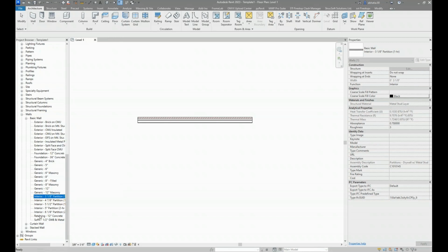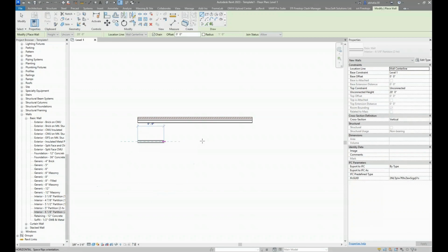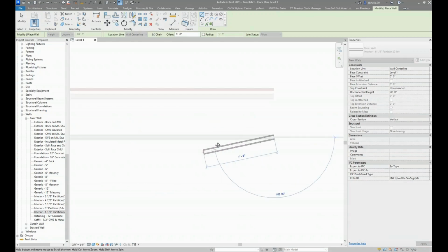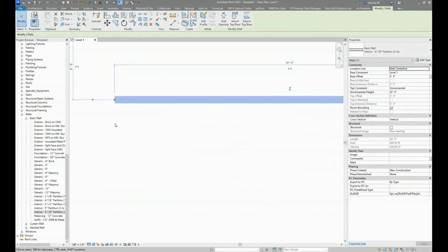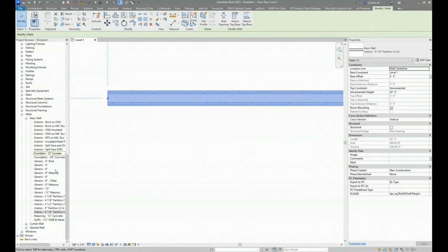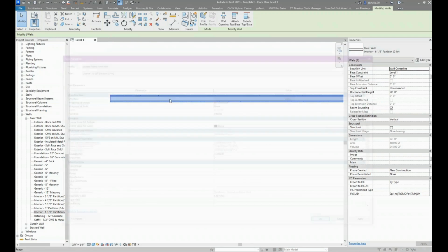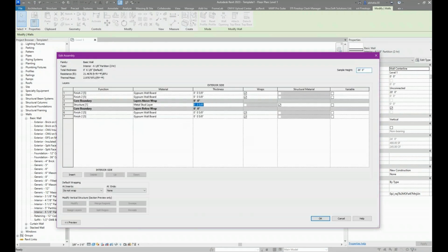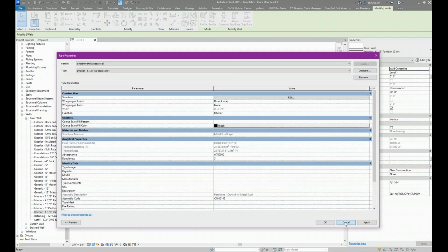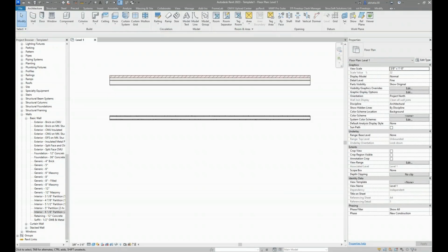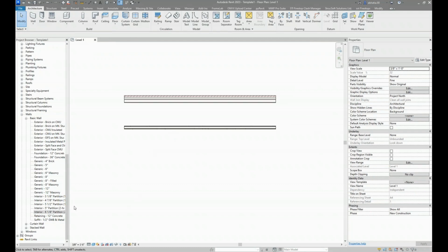Let's go ahead and create instance. Let's draw this one. That's the only thing I don't like about this template is that the wall naming conventions for the interiors, it's 618, but that doesn't tell me what's the interior layer thickness. So I have to kind of go figure out what that thickness is by actually checking this out. But the benefit of our multi-layer template maps is that it tells you the structural layer thickness, so you can kind of get away with just using them.